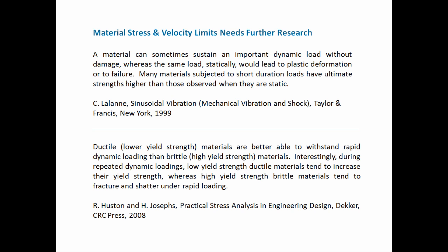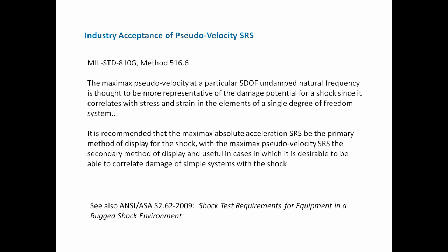characteristics of these materials. Of course, when we're talking about shock loading, there are people who say we need to be doing everything based on strain rather than stress, and there are some good arguments for that, but that's maybe in some future webinar. I think we've talked about some of these things already. Pseudo velocity, which Gaberson championed for many years, he and others think it should be the primary metric for our shock response spectrum specifications and testing.